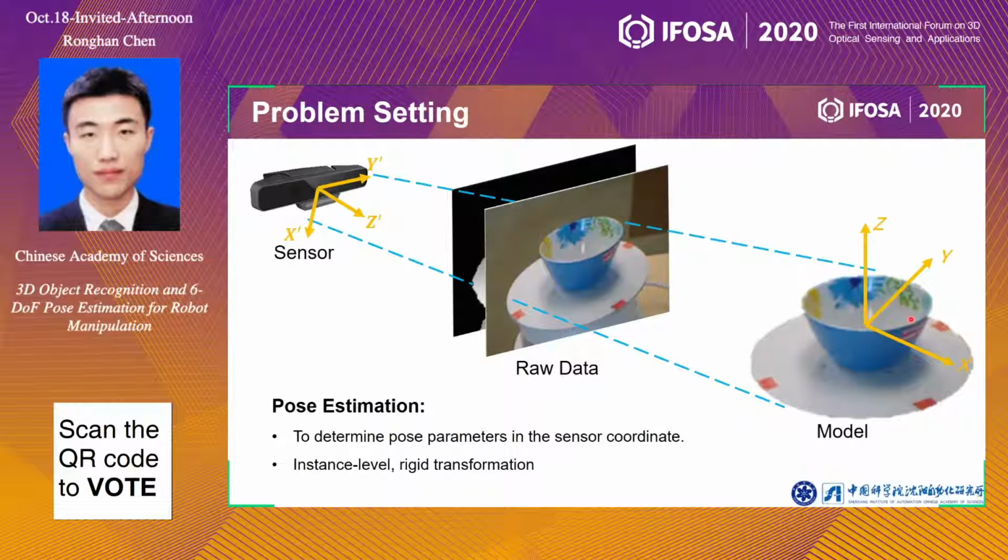Then when testing online, we first recognize and localize the target using segmentation or detection techniques. Then the pose can be estimated. Since the object is rigid, the grasp labels in the database can be directly transferred to the scene using the estimated pose.